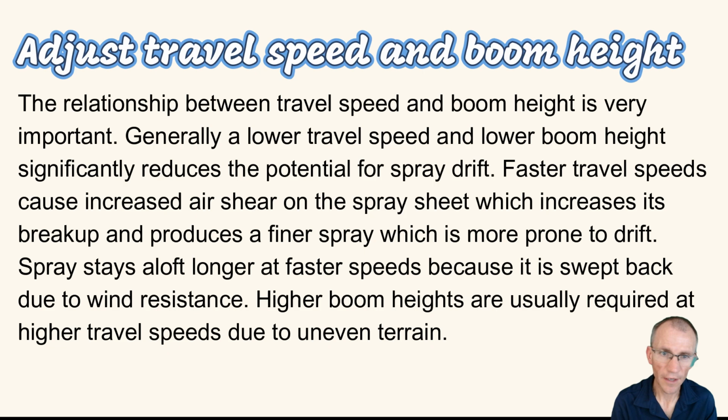Another way of reducing drift is to adjust travel speed and boom height. The relationship between travel speed and boom height is very important. Generally, a lower travel speed and lower boom height significantly reduces the potential for spray drift. Faster travel speeds cause increased air shear on the spray sheet, which increases its breakup and produces a finer spray which is more prone to drift. Spray stays aloft longer at faster speeds because it is swept back due to wind resistance.